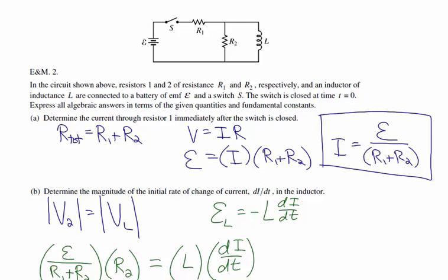And so when we try and make the current go to 0, Faraday's law and Lenz's law says that it tries to oppose that change. There's a current that gets generated that tries to oppose the change in flux. In fact, the current that's going to be flowing immediately is going to be the same current that was flowing through it right before the switch was opened. That was our answer to part C. What we have now is this inductor, and it's going to push current around, and it's going to flow through resistor 2. We have a little loop there.